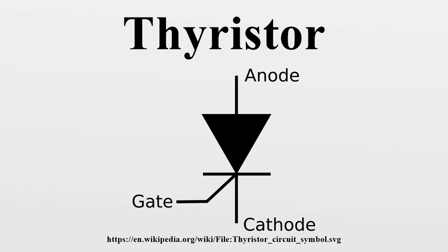Types: AX, ACST. AGT, anode gate thyristor, a thyristor with gate on N-type layer near to the anode. ASCR, asymmetrical SCR. BCT, bidirectional control thyristor, a bidirectional switching device containing two thyristor structures with separate gate contacts. BOD, breakover diode, a gateless thyristor triggered by avalanche current. DIAC, bidirectional trigger device. Dynistor, unidirectional switching device. Shockley diode, unidirectional trigger and switching device. SIDAC, bidirectional switching device.